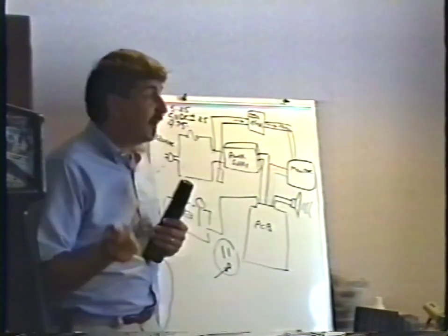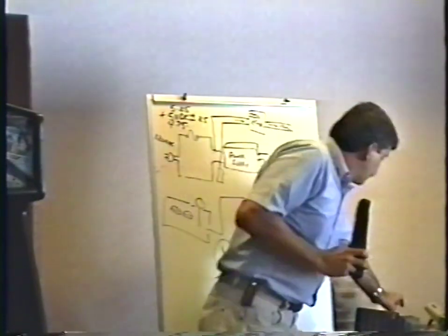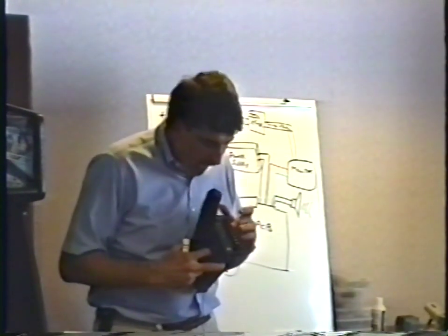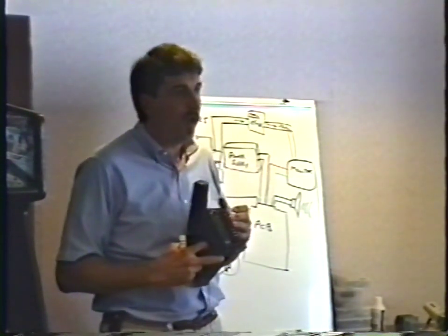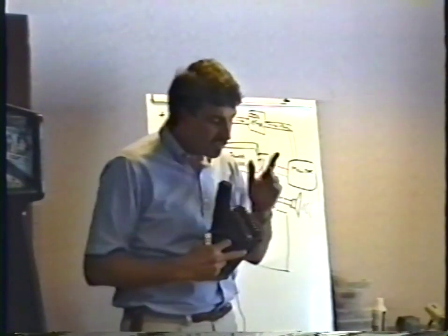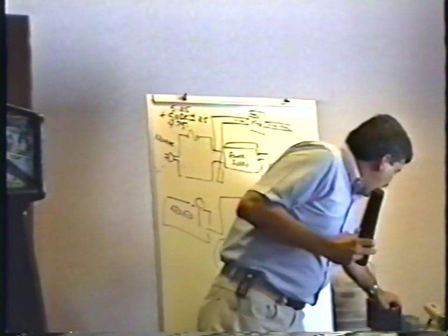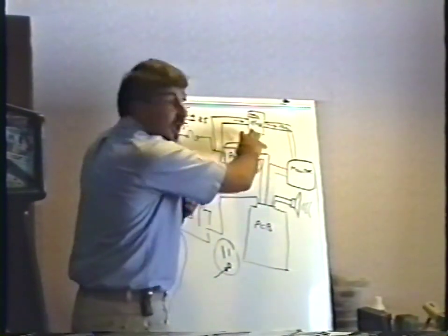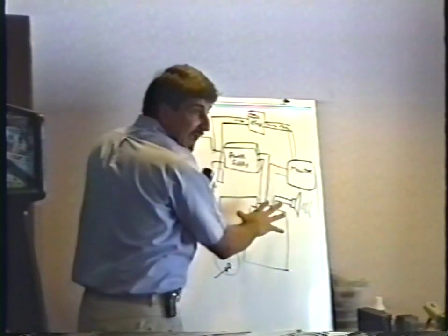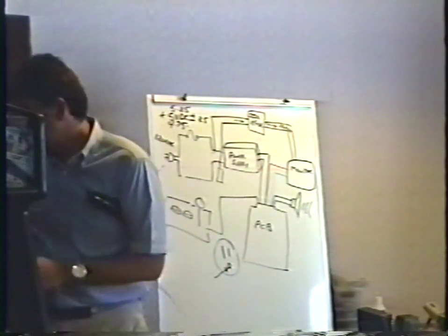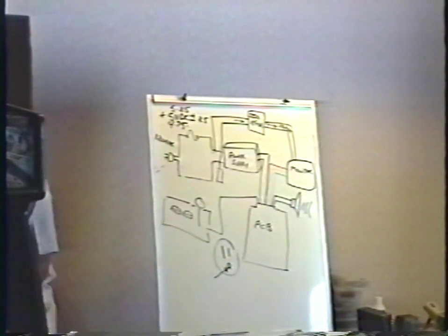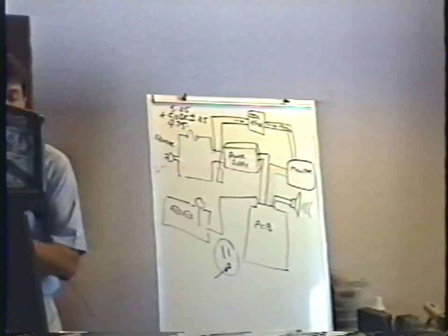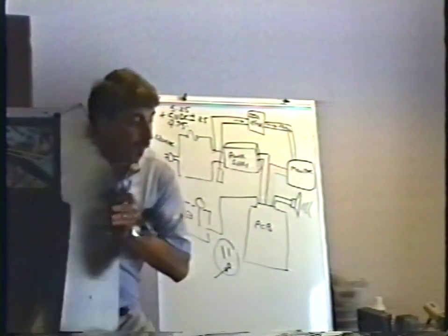But where the heck are you going to check the voltage? Well, the logical place is the same place you checked it before. You go, well, I'll just put one meter lead here on ground and the other on plus 5 and adjust it to 5.1. Not even. The reason why not is that by the time the current gets out of the power supply, through the wiring harness, through the connector, it's real easy to lose a few tenths of a volt. And since the voltage is so critical, it's very important that it's 5.1 volts on the logic board.